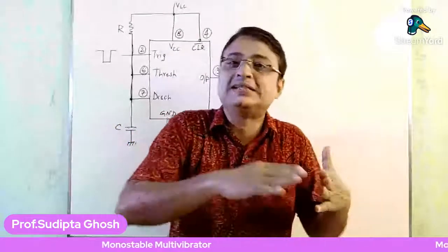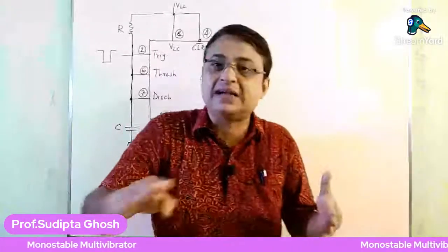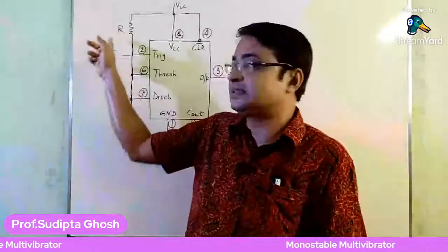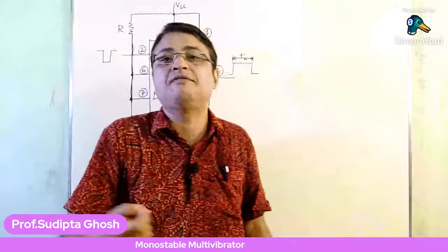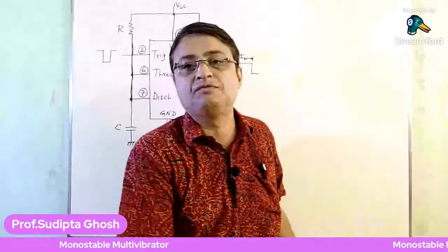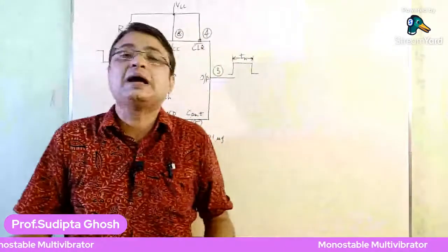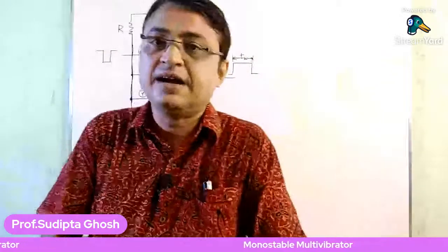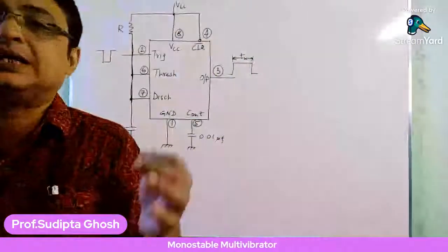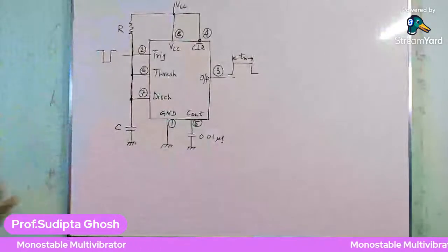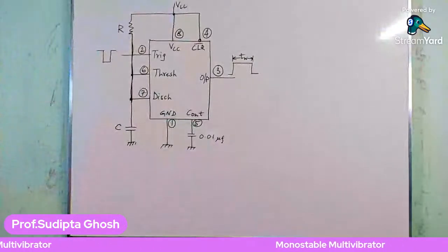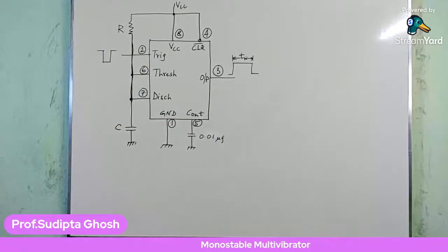So that is the charging path, but this charging path has a resistor, as I have already discussed. By having a value of this resistor R, the capacitor goes on charging right now, because the discharge pin is disconnected from the discharge transistor and the capacitor finds the value of VCC.